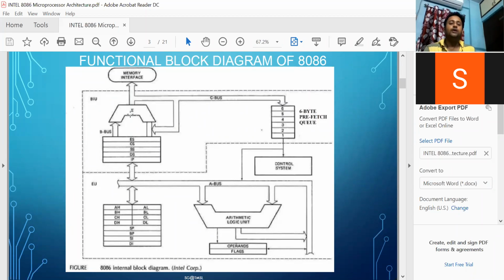Okay, so here these are the registers for special purpose to store the segment addresses. That's why these are called segment registers. One offset register is included in this position, that is the IP, because first you need to access the instruction for any operation using the microprocessor, that is, the execution of instructions. Now we know that every instruction has two parts. First is the opcode, second is the operand. To fetch any instruction means to fetch the opcode first, then the operand part.